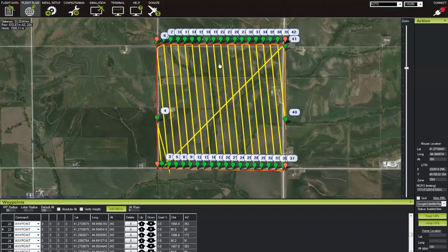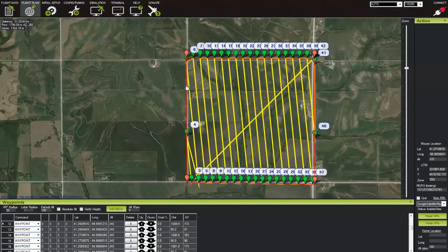If you routinely adjust your angle of flight for wind direction on days that you are flying, over the course of several missions you will be able to generate a very tight set of photo data for analysis that can be referred to by your crop monitoring program, or for generating DEMs and so forth using Agisoft PhotoScan Pro or Pix4D. Once you have programmed in your grid pattern, you're always going to want to program in a landing waypoint as well, so that you can perform an automatic landing.